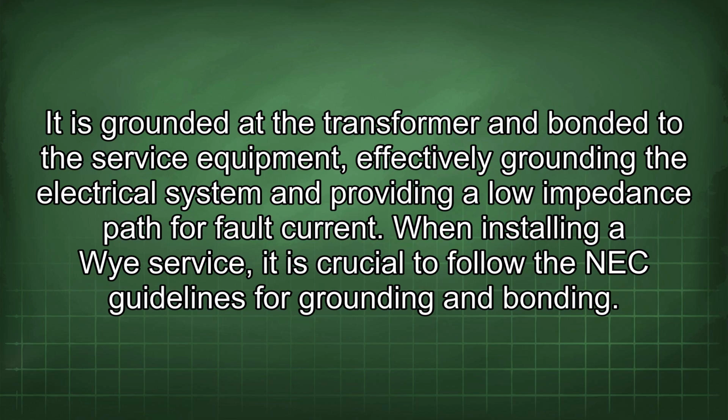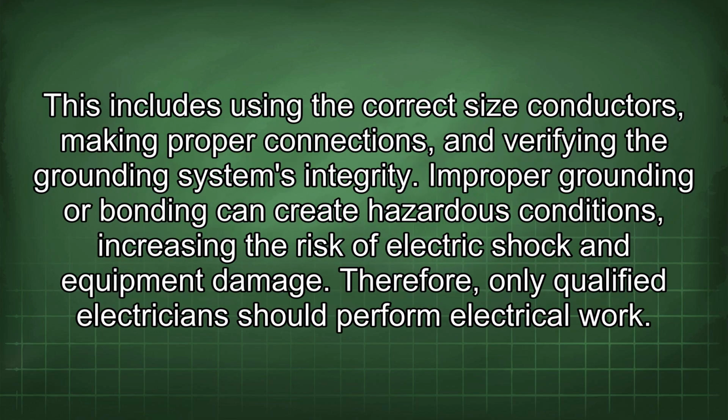When installing a Y-service, it is crucial to follow the NEC guidelines for grounding and bonding. This includes using the correct size conductors, making proper connections, and verifying the grounding system's integrity. Improper grounding or bonding can create hazardous conditions, increasing the risk of electric shock and equipment damage. Therefore, only qualified electricians should perform electrical work.